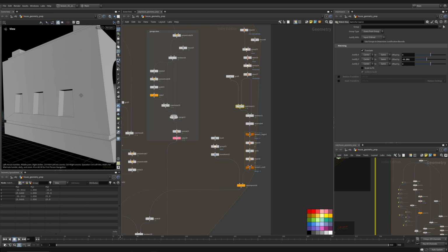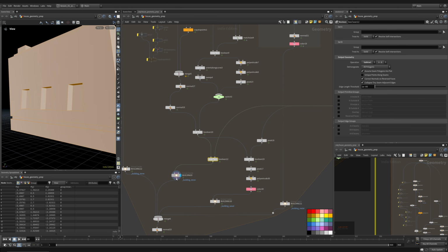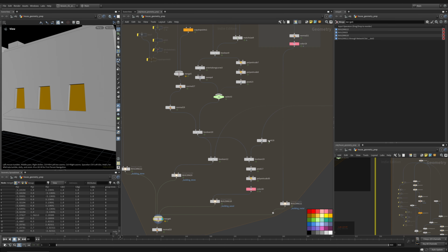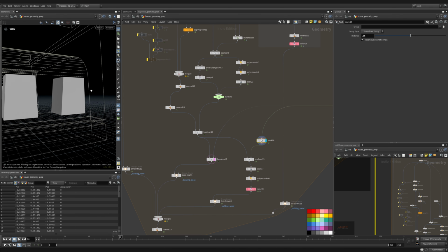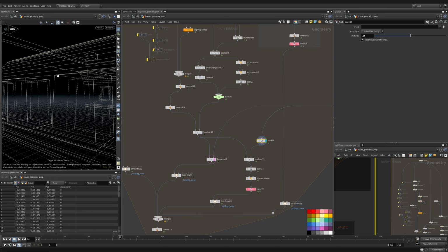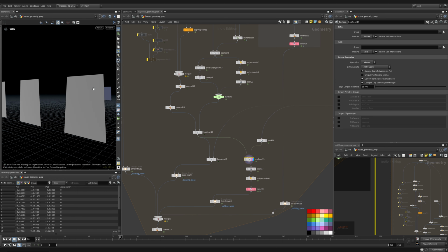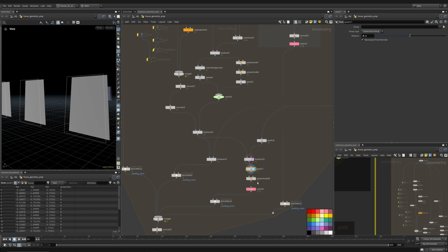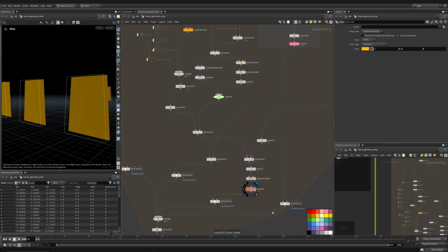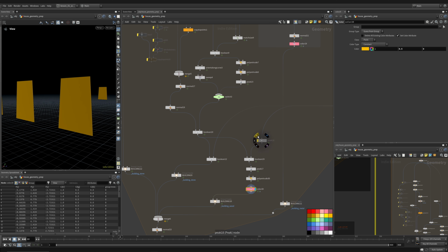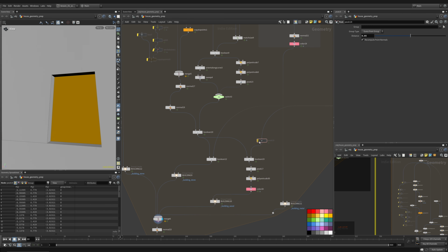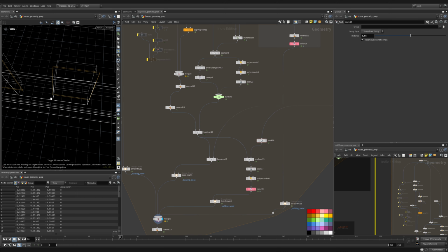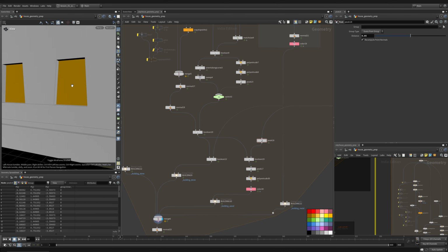So there we go. What I wanted to do is cut the windows, keep those as windows, and then add some geometry inside the windows. You see, I'm going to template this flag inside here, but I want them to always intersect. So I always want the window wood, which is this thing here, to be bigger than the actual hole itself. And that's done with this peak. So here, when I merge these together, and you'll see if I actually peak this in the negative direction, this wooden frame, you see how it intersects this wall? I could shrink that.